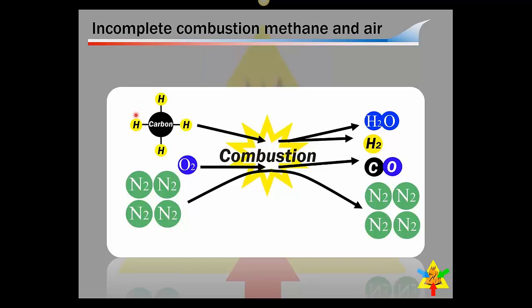So now look what I've done. I've got the same natural gas, but I reduced my air by 2/3. Okay? Now let's look at the combustion process. We run it through. So I still recreate some H2O, some water, but now I've got these unburned hydrogen molecules, and that's what we call soot. Okay? There's not enough oxygen for these guys here to combine to create more water. They're just kind of passed through unburnt. Nothing's happened to them. This is soot.